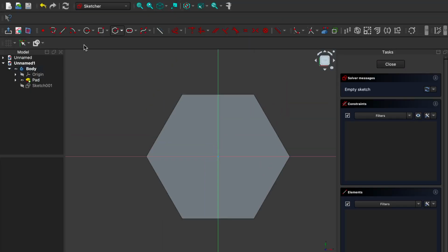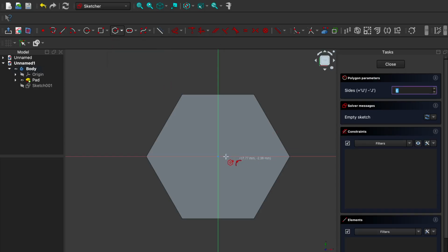Okay, I'm going to put in the same shape that I used at the beginning, a hexagon, hexagone in French. If we recall, the first time we used 62, here we're going to use 60. That way we have a thickness of 2 millimeters for the wall. Click OK, like OK is enter, and the angle just means I'm going to construct it at the same time.